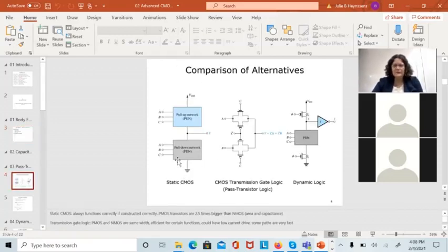We looked at 3 different types of ways of doing standard logic. Static CMOS, the most reliable and robust. Pass transistor, and we were looking at a hybrid pass transistor dynamic logic circuit in memories today that people actually used. So pass transistor gets used, and the basic rule for this is what's on the gate and what's on the drain gets ANDed together and comes out at the source. If I tie 2 wires together, I get the OR of that.